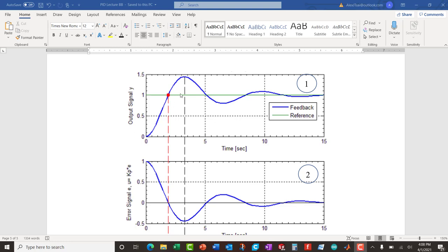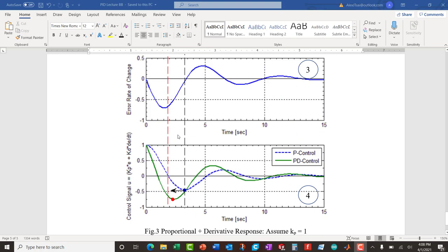And that's what D control does. It reduces these oscillations that overshoot and makes it faster, so you are essentially bringing all these curves closer to a step looking function, so that Y would follow R. Okay, and that's why we use D control.